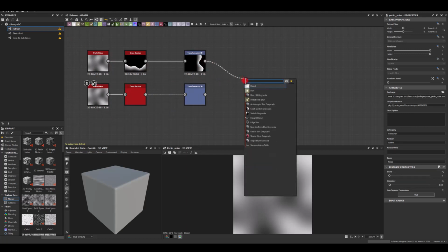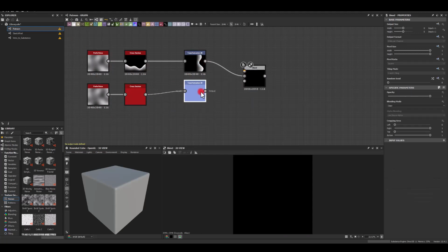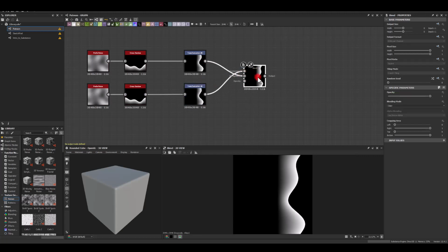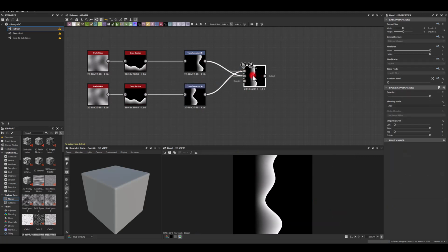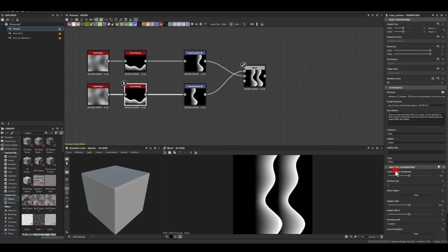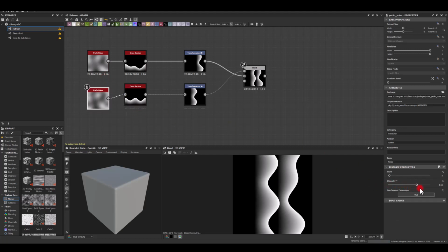and I'm gonna blend those two together. Now I'm gonna change the offset here to be slightly behind it, and in here I'm gonna change the blending node to add. I'm gonna go to cross section and change the coordinate to get a slightly different look for this wave pattern. Probably increase the perlin noise disorder of it as well, just to make sure we are getting something slightly different.